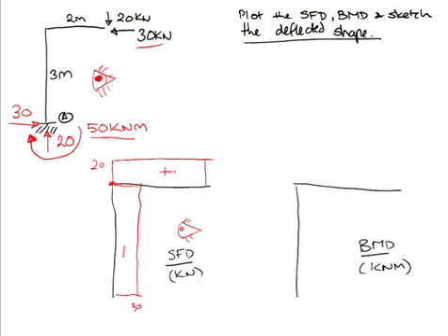So moving across to your bending moment diagram, a positive shear force we say is a downward slope, and when we look at the vertical face, a negative shear force is an upward slope. Now, because my shear forces are constants, your bending moment will be linear. Your bending moment is just a result of a single point load times a distance, force times distance.